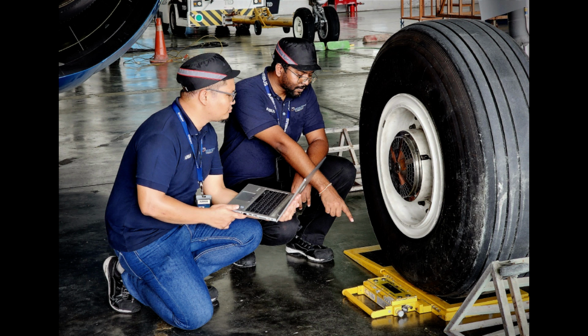The pilot in command, PIC, is responsible for knowing the weight of the load, CG, maximum allowable weight, and CG limits of the aircraft. The weight and balance report must include an equipment list showing weights and moment arms of all required and optional items of equipment included in the certificate empty weight. Weight and balance records used in accounting for and correcting the CG location are reliable for only limited periods of time. For this reason, periodic aircraft weighing is desirable.